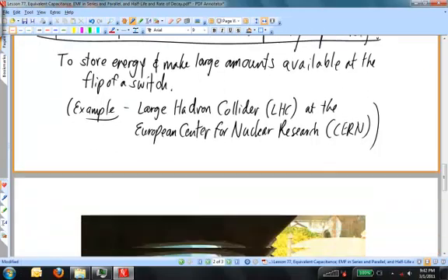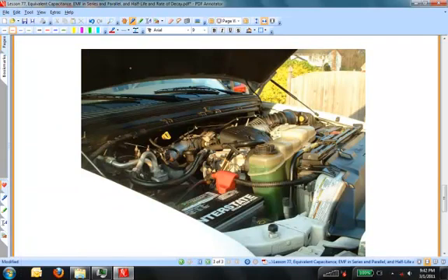First, batteries in parallel. One common place you'll find parallel automotive batteries is under the hood of vehicles using diesel engines. You can see two batteries in this vehicle, one on this side and one on that side. I currently drive a Dodge Ram 2500 pickup truck with a diesel engine. These engines require a lot of torque to get them started, and a single 12-volt battery would not supply the current needed to get the starter motor to turn the engine over, especially on a really cold day. So, under the hood, you'll find a pair of batteries connected in parallel. It's still a 12-volt system, and that pair of batteries supplies the current needed to crank the engine.